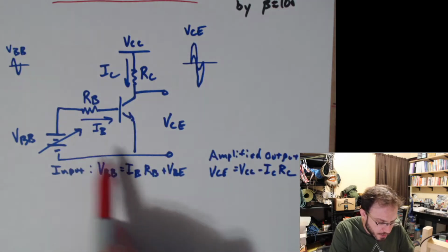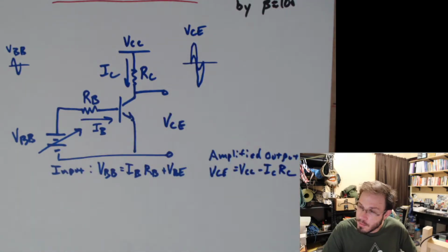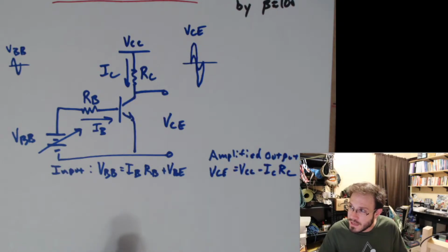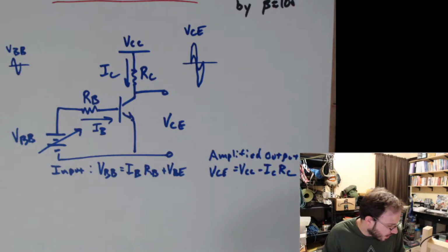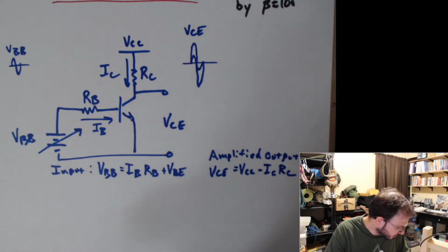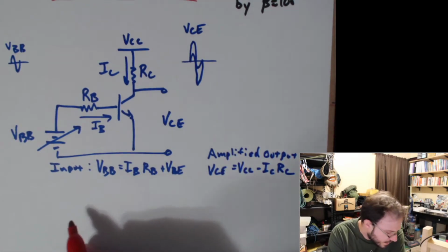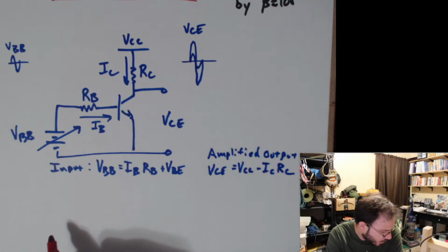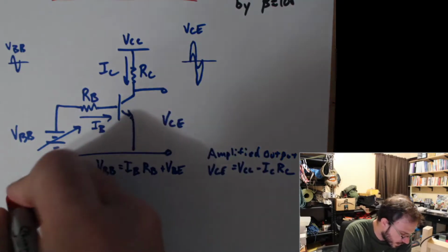So we will eventually be building this up into our voltage divider bias, which is a pretty good circuit because, like I said previously, our voltage divider bias negates those changes to beta, and then it allows us the flexibility to just control the gain based off of the resistors, so we don't have to worry about beta changing on us and changing what our gain of the amplifier is. So let's go ahead and talk about the relationship between our input and our output voltage.